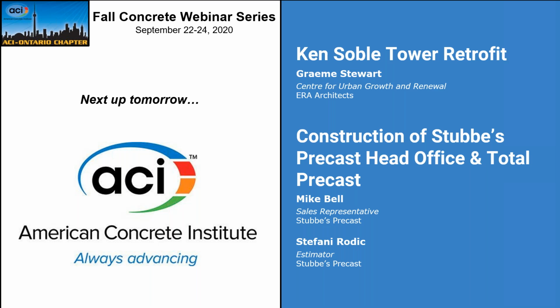But for instance, a lot of the mixes we used almost identical mix designs, even though there was that variation, and we usually just adjusted the water cement ratio or adjusted some of the supplementary materials to tier it down in the way we did. But we very much over designed for all of the mix designs because of our lack of experience initially with these projects.